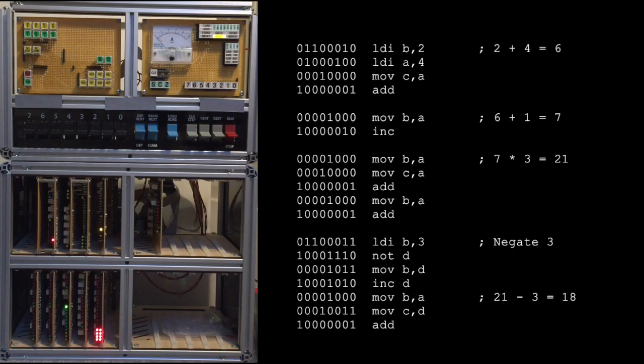Right, we've got everything we need now to step through this program, so let's make a start. To begin with, I'll operate the clock line by hand, but later on I'll let the clock board take over. Remember that there's no memory, no program counter and no incrementer, so I'll have to stop the clock after each instruction, enter the next op code and then start the clock again. When those next cards are complete, we'll be able to enter the full program and let the computer churn through each line on its own. Right, anyway, off we go.